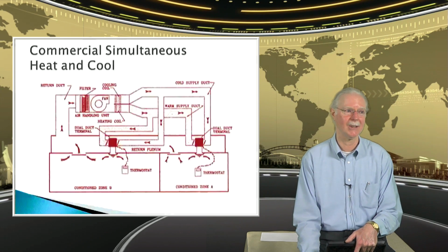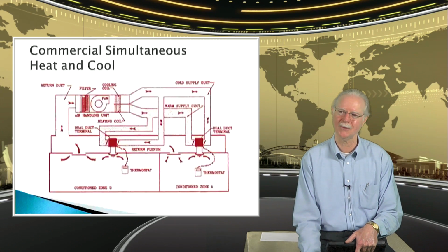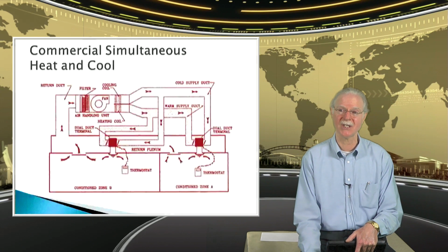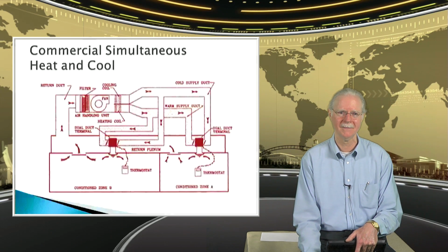Now we have just the opposite thing going on. And we always have something that we call overshoot. You set the thermostat, and it may or may not shut off just at the temperature that you set. But at the very least, there's some delay. And what a lot of people forget is, if I turn the thermostat all the way up, will the office get any hotter than if I set it to the temperature I want it to be? It doesn't get hotter any faster. It's still going to take a while for the system to catch up.